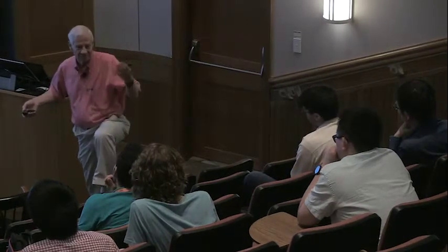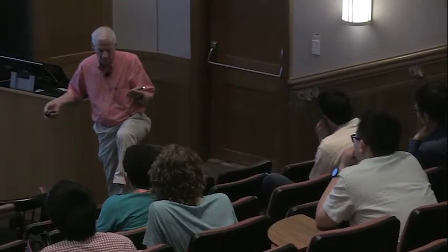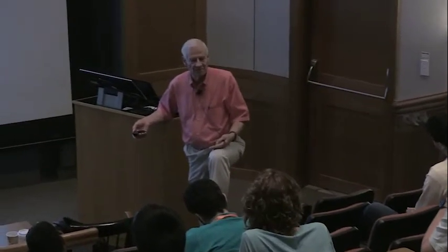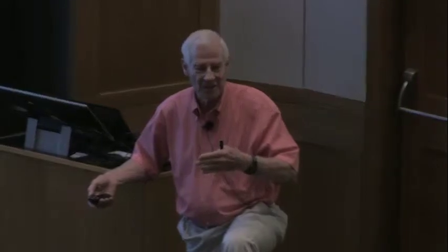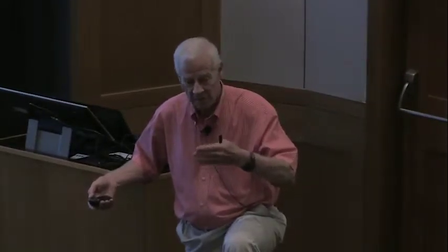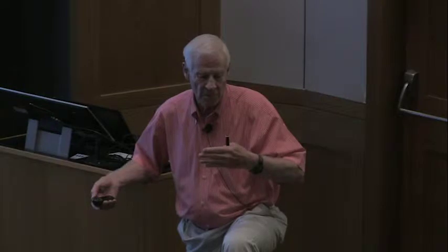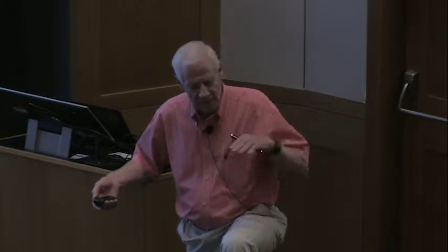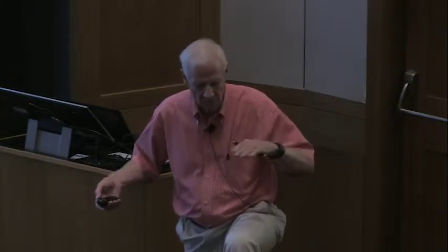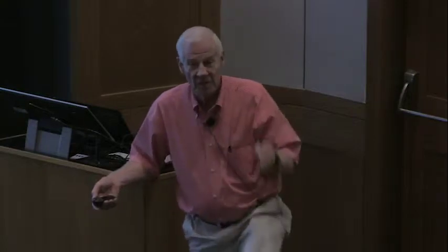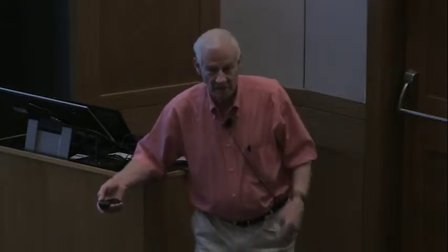I mean, you can do it. If you're interested, why would you do this? You're interested in spatial distributions. Well, if you're going to do PLIF, you get the spatial distribution in a plane, and you have to interpret it. That's the hard part. You can scan your plane. So to me, for getting the spatial distribution perpendicular to the plane, I think it's just better to scan the plane. But I know that everybody who's doing this right now is talking about volume and so on. I think the jury's still out on that.